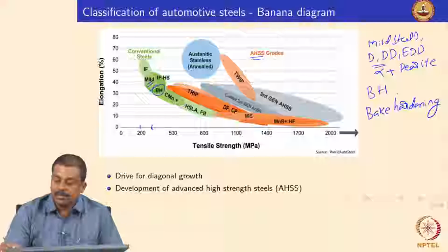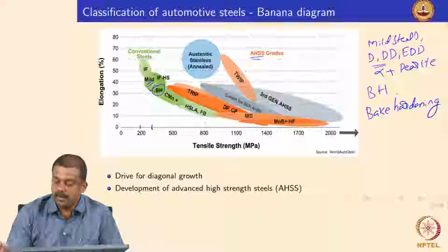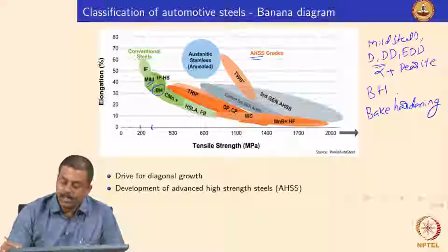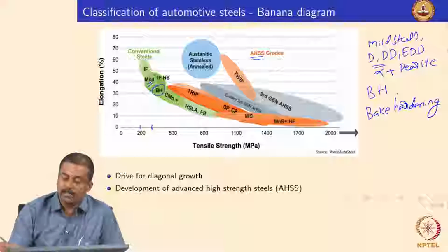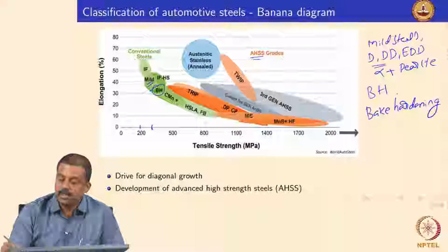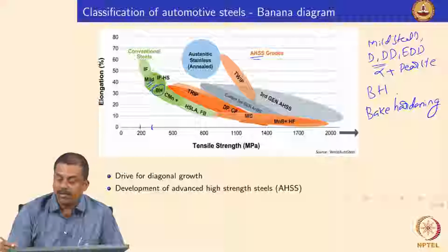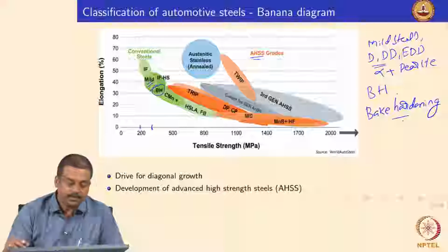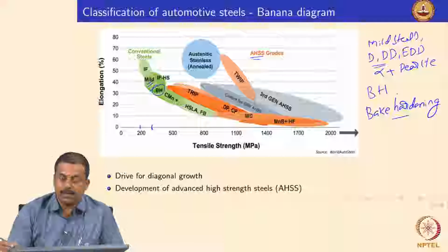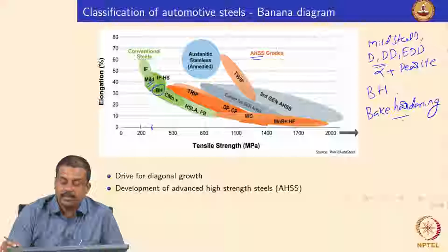So this steel also contains very low carbon concentrations, in a few tens of ppm, parts per million. And unlike the IF steel, the bake hardening steel does not have microalloying additions. So we deliberately leave carbon in interstitial positions. Carbon is actually present in the interstitial position for one very important reason. Again, this steel contains very low carbon, and the carbon atoms are kept in the interstitial positions.